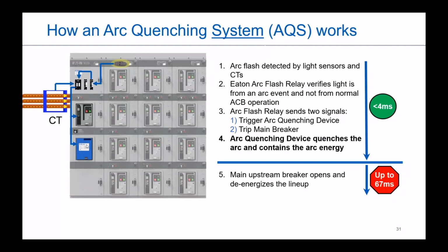The way our specific system works is our arc quenching device is a one and done style. So after an event, you would have to take our little blue box here out of the system. Say, for example, you do not have a spare on hand though. We do have a way for you to be able to return this to service without the arc quenching device.